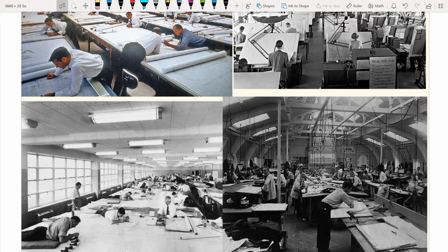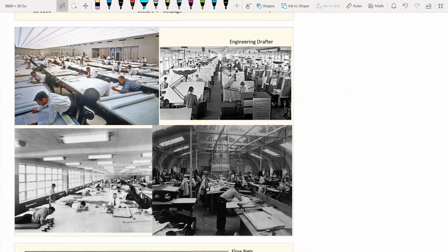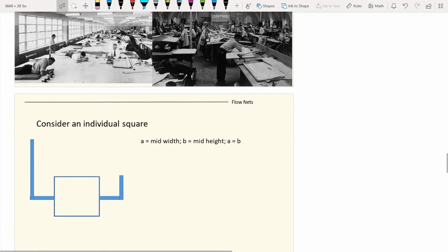And if the heads at some critical locations of the dam have become too high, they can calculate the potential head because they know the total head and the elevation head. And if they realize the potential head becomes too high, we learned in lecture 3 that you can calculate the water pressure from the potential head. If the water pressure is too high, you can topple the whole geotechnical structure, which means the dam could fail. So very important, those are very important calculations for us engineers.